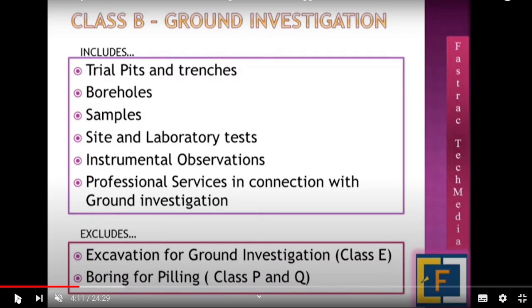and for this we may require the service of a geotechnical engineer or those who are experts in this type of test. So how to measure, how to pay for these things, that depends on class B of CESMM, that is ground investigation. But don't think that everything related to ground investigation is included.